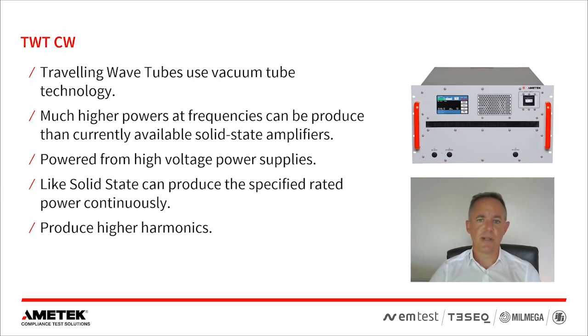One point to note though is that TWTs have a typical 25 dB higher noise figure than the solid-state solution. This can have a significant impact when you multiply by the bandwidth.